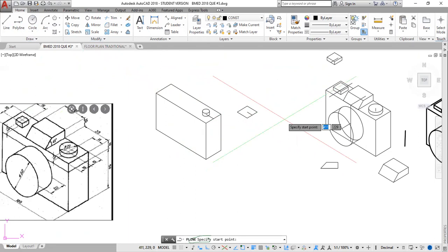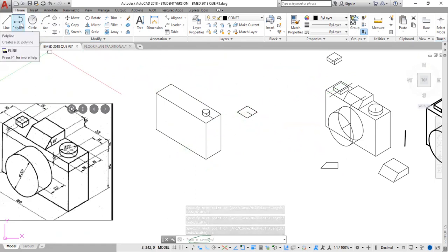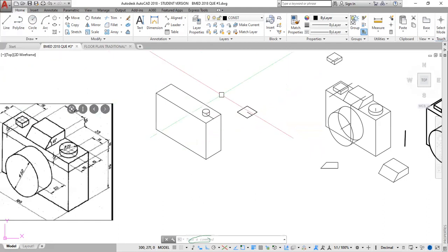Polyline, so I'll click here, there, here, there, C. Which mode is of use? Polyline, this one right here. No, sir, the mode. Isodraft. So I'm going to move. All right, so now I'm going to copy this upward at a distance of 5 millimeters.